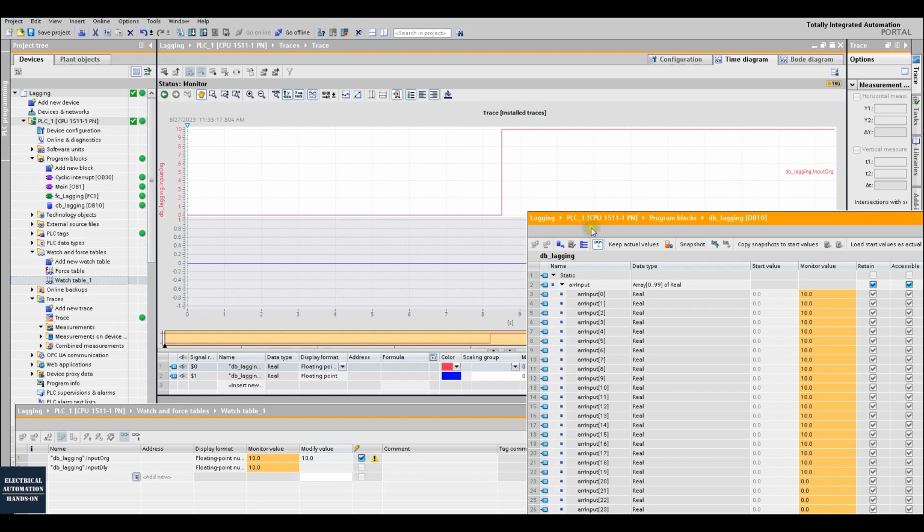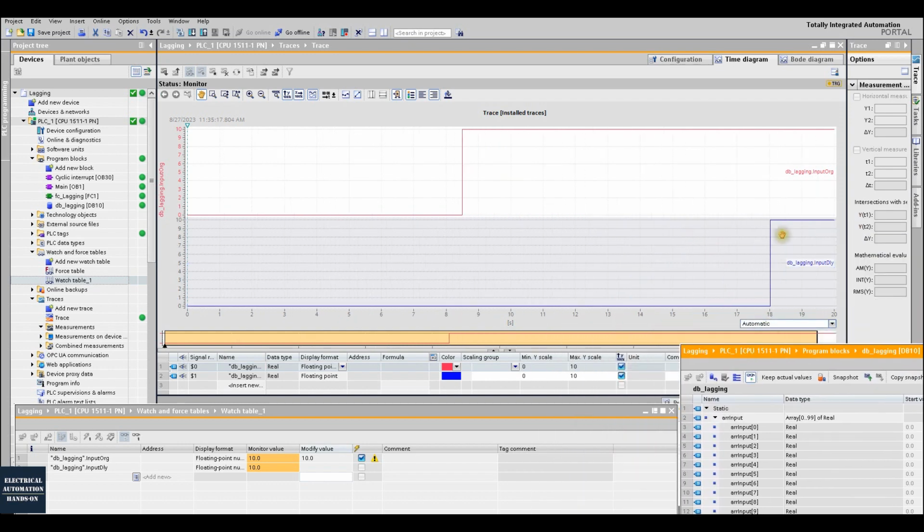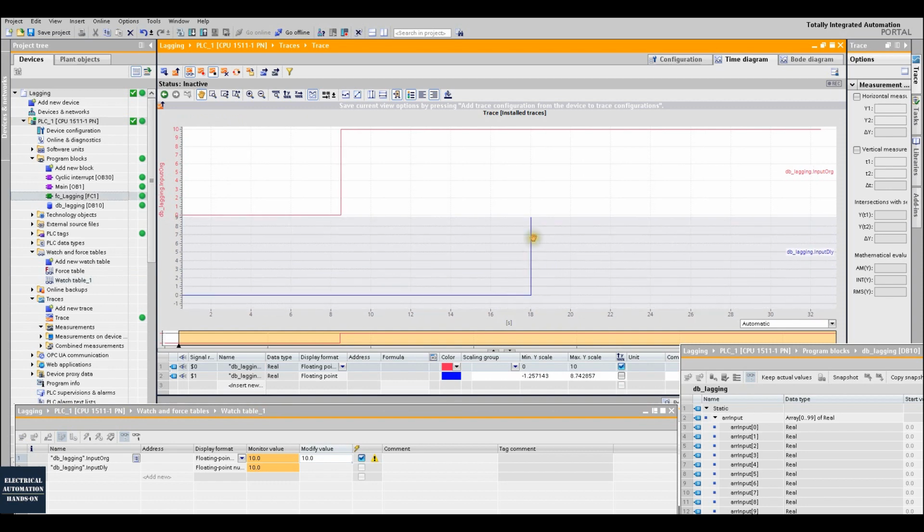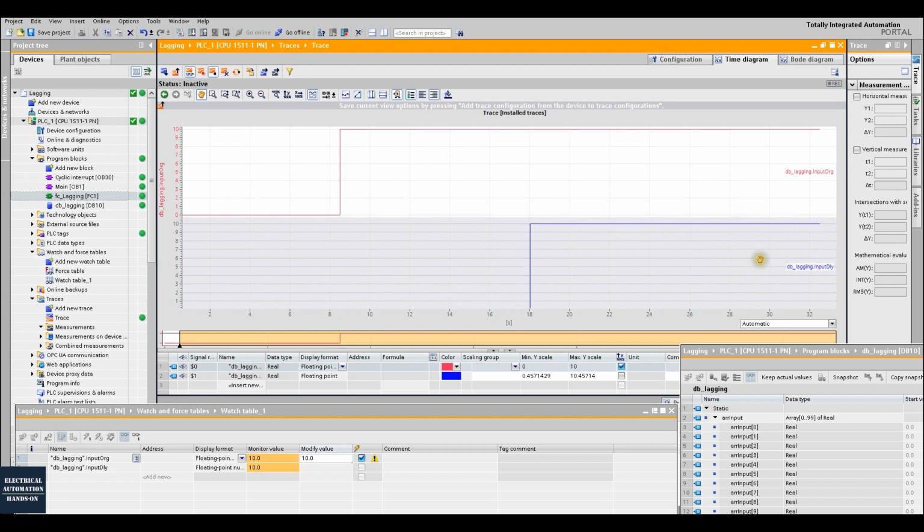We will see along the time, this buffer will be filled. After 10 seconds, we will see this blue line turned on. So this is the delay. Okay? So we see this function achieved here, and we can stop this trace. I transferred this input at this 8 seconds. After the 10 seconds here, we got this output here. Then this blue line, this variable, can be used as the real input of our transfer function. So we can use this logic to simulate this delay behavior.